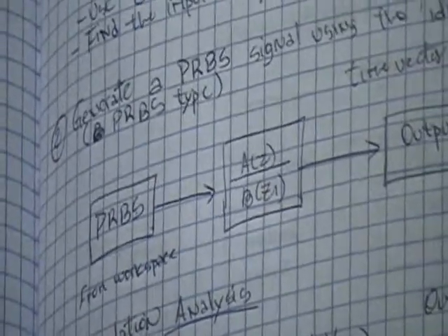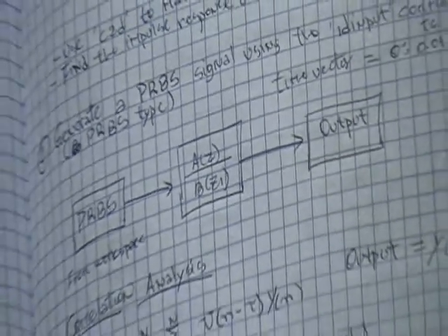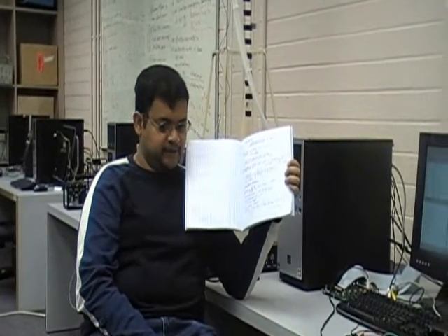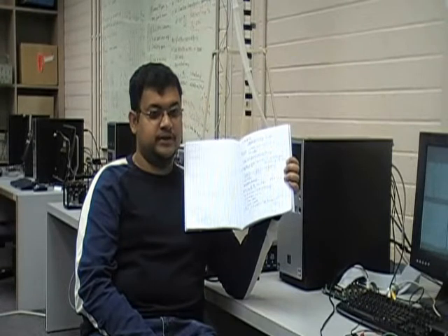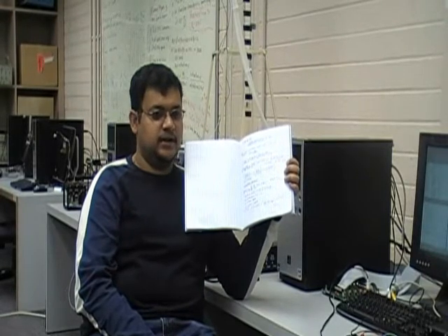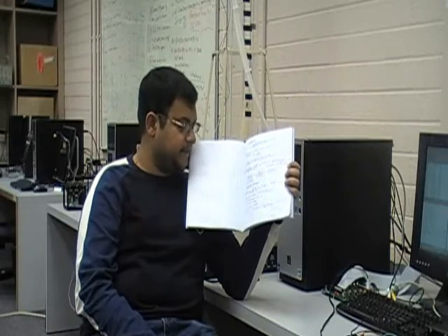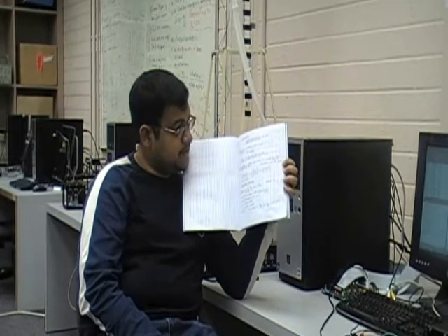The reason we use this kind of a signal to excite our system is because in order to do system ID, like to get a correlation analysis or do least squares, which we'll do in the labs after this, we have to meet something called the persistent excitation criterion. And if you don't excite your system enough, then you will not get good data. So here's what we do.